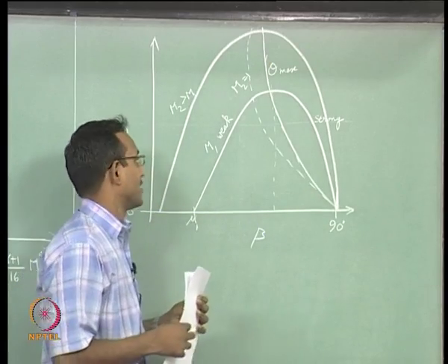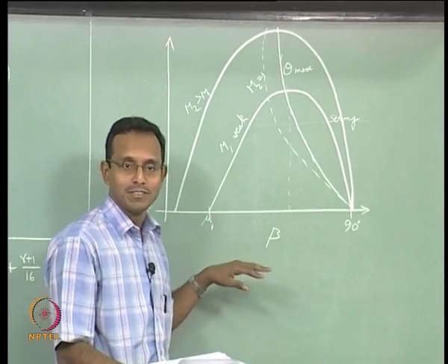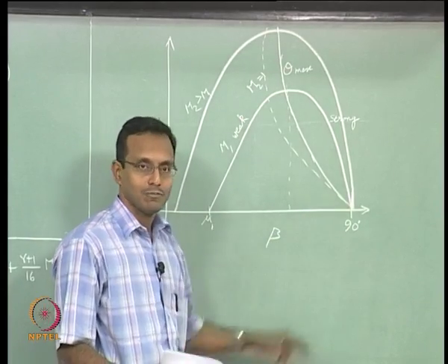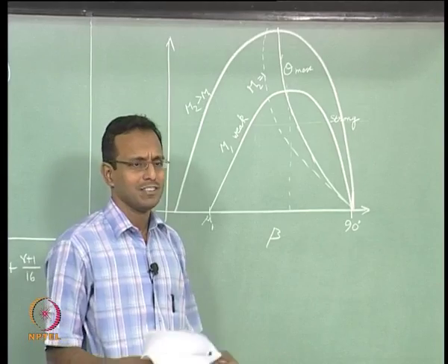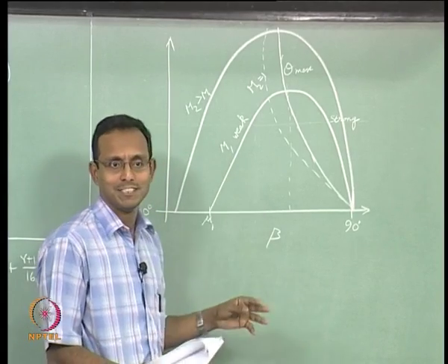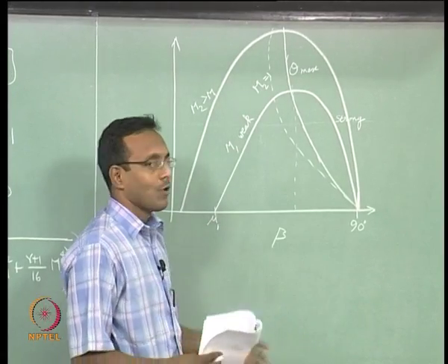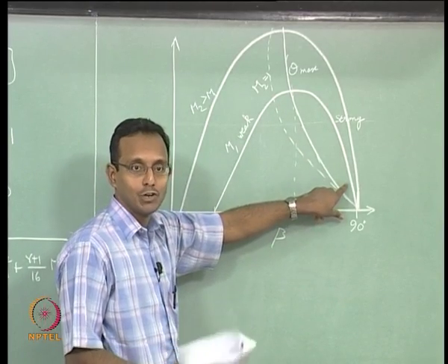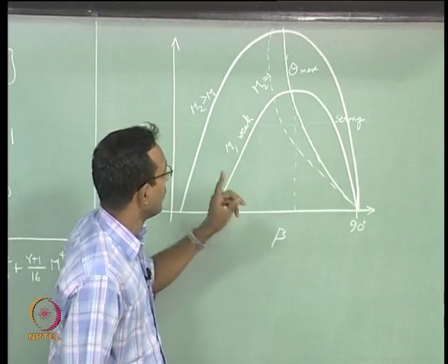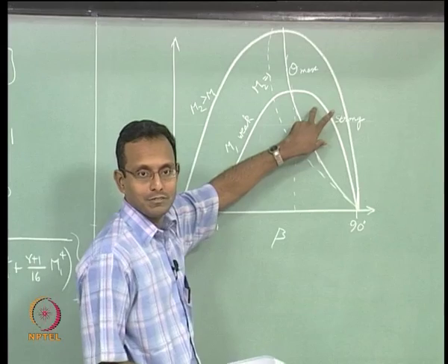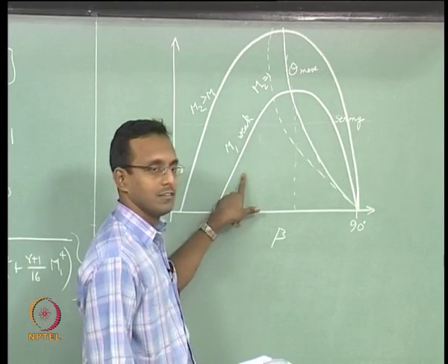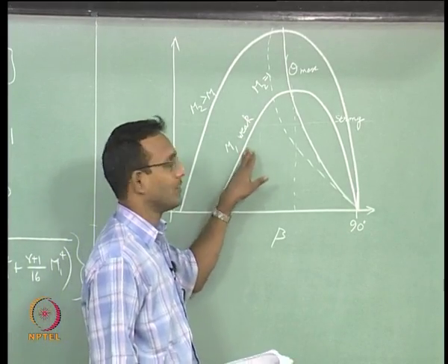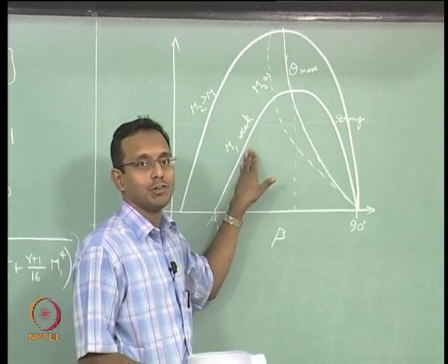Okay. I actually did the calculation for all Mach numbers and all betas and found the m2 for all of them, and then put a contour of that along here. Of course, you can find an expression for when m2 becomes 1, but it is not simple enough. So, I just did the graphical method, it is easier for me. What you have to note is, if I think about a strong oblique shock, then I am going to have only subsonic conditions behind the shock. If it is weak, for low values of theta, I will have supersonic flow behind the weak shock solution, if you want to think about it.